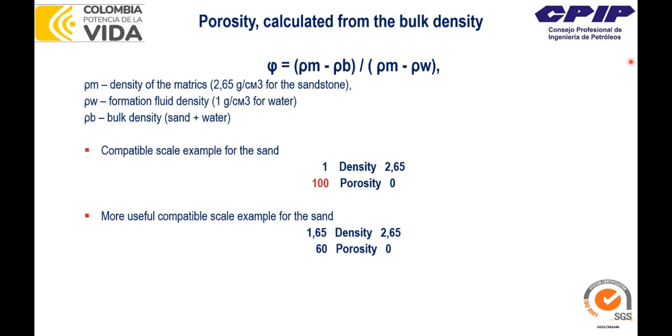So the porosity, expressed as a decimal fraction, can be multiplied by 100 to express it as a whole number in porosity units. For example, you can express it as 0.6 or 60 porosity units. This multiplication is much like multiplying by 100%, but avoids the confusion of having the units named percent. When shale is present or the porosity in the formation contains hydrocarbons, a correction is required to the apparent porosity read on the log scale.